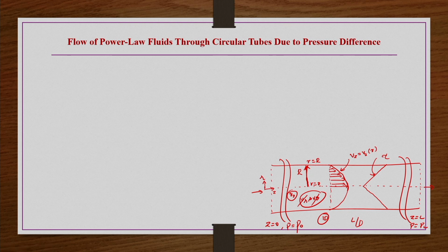the wall, right. So, what is the shear stress that we are expecting in this case, because it is one dimensional motion? Then tau Rz we are going to have, and that is also a function of r, and that function is a linear function, as we understand through our capillary viscometer case also. Indeed, this is completely the same as a capillary viscometer, but the context that we are seeing is different.